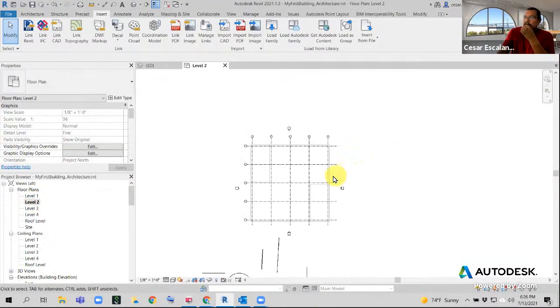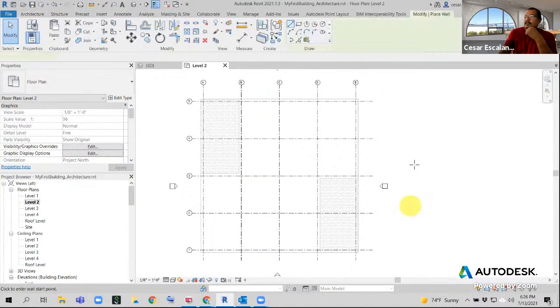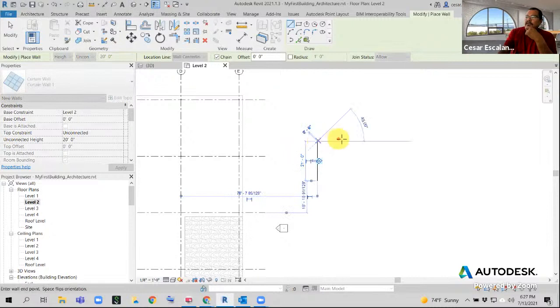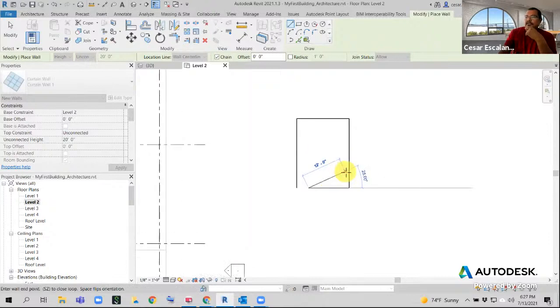And all we're going to do is create our chain of storefronts using the clockwise direction. And why is this? Because of the exterior side when we create a wall, I think I showed you guys this. When we create a wall, the direction of the exterior side depends on the direction of the wall creation.